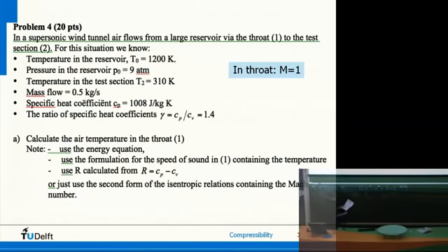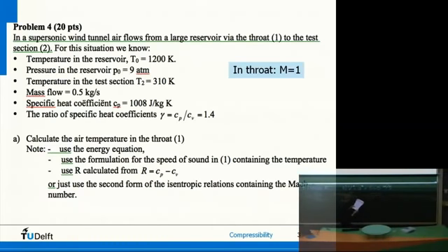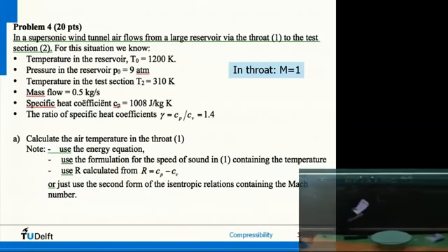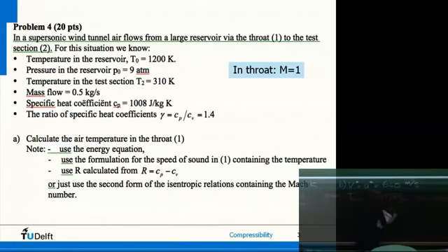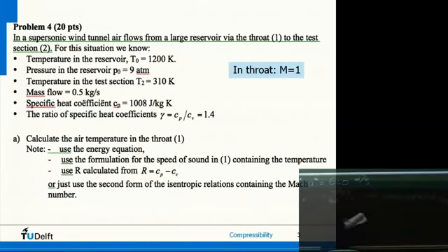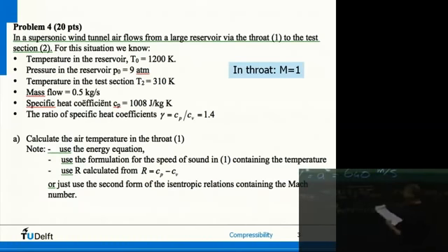Okay, let's try. So first, A test. So A test is then equal to the square root of gamma, 1.4, R, 288, and the temperature given, 310, right? So that's the easy bit. We find then that the speed of sound is 353.5 meters per second.